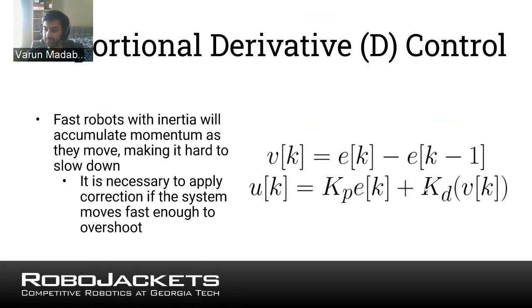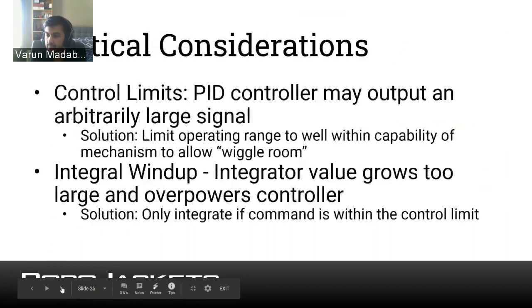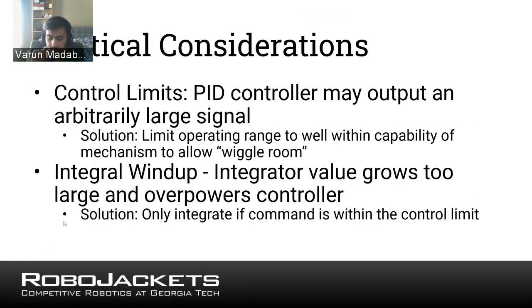And we can multiply this by another constant, kd. And this works just like proportional control and derivative control. So in various different cases, you may want to use P, PI, PD, or PID control. And you can just test out different combinations of the 3 to see what works. So PID is really useful.